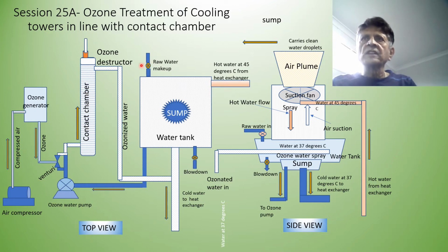There is a raw water input, top up, and there is a blow down where you can reduce the water levels, reduce the TDS by blowing out some water and topping up with raw water to make up the volume loss, normally not only through blowdown but also through evaporation and water sprays, etc., that may also lead to reduction in the volume of water in the circulation.